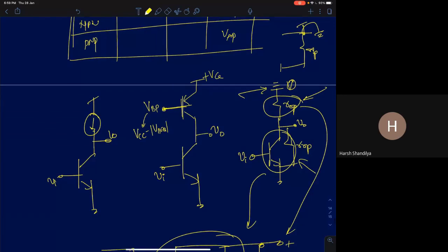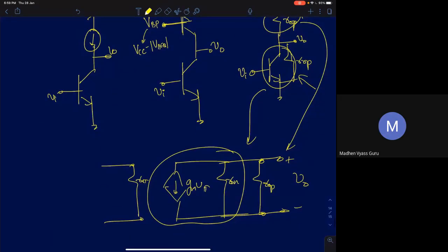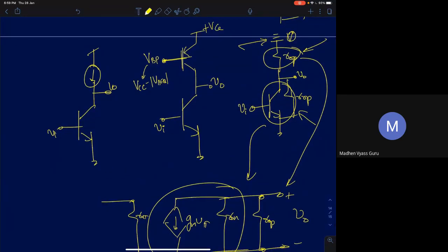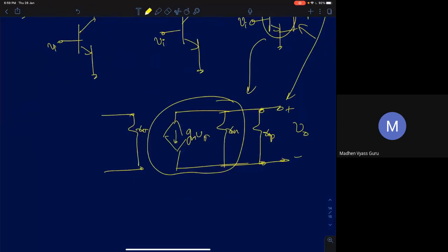Okay? Sir, shouldn't there be another current source of ICQ? Shouldn't there be another current source of ICQ? No, this is the small signal model, what I have drawn here. Okay, so you've shorted it. No, you opened the circuit. Okay, fine. You should make current as 0. Okay. So this is the small signal or incremental model.